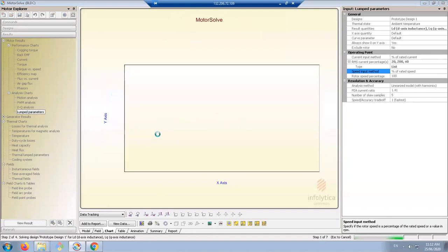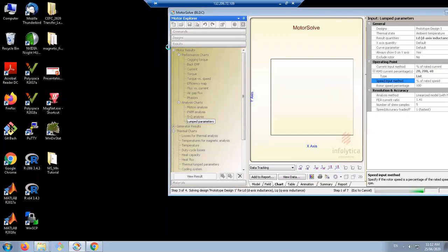That's exactly what I was talking about, because once the inductance changes, it basically means that the motor parameters change and motor behavior will change. So here you can actually see the two decoupled LD and LQ. In practice, LD and LQ are not decoupled. They are highly coupled. Let's see if we have that here.